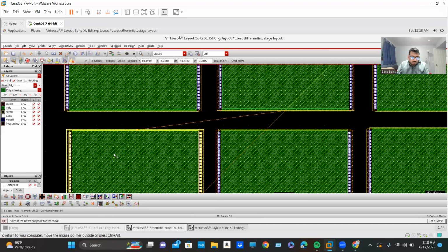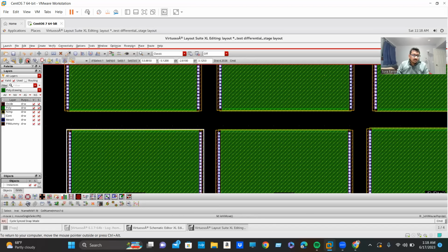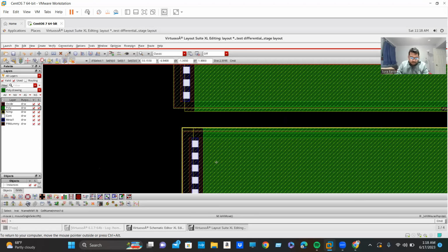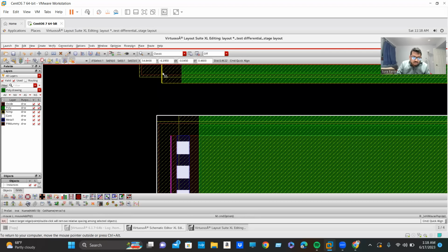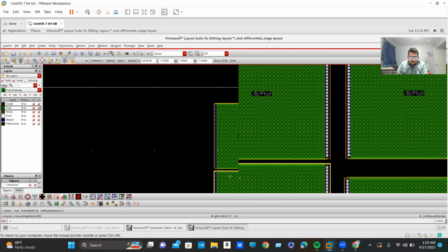Let's say move it. Okay, for aligning, you should keep it like a plus. Then you can move it orthogonal and diagonal. Don't move corner to corner, because if I do that, it will be very hard to align all of the stuff. Okay, so right now I am just keeping it a little bit up. I just move it by pressing M. I select it. I hit A from keyboard, and I want to select this layer. Okay, now it is aligned.